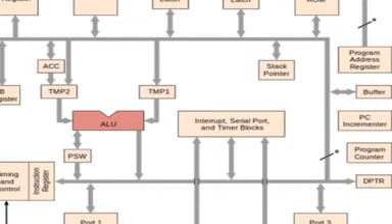So A, B, DPTR, PSW. DPTR means data pointer, then program status word, then you have interrupt priority, interrupt enable, IP, IE, then TCON, SCON, and all such ports. All of these come under SFRs. Of these, a few are byte addressable and a few are bit addressable.